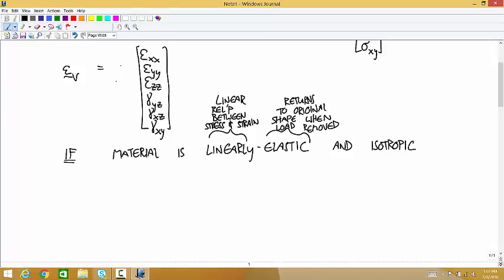Nothing's perfectly elastic, but it's basically elastic up to a certain point. When you cross that point, you bend it permanently and it won't go back anymore. But when you cross that point and it becomes deformed, and you remove the loads and you put the loads back again, does it go back to elastic again? Yep, it does, but it has a new resting shape.